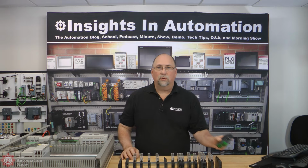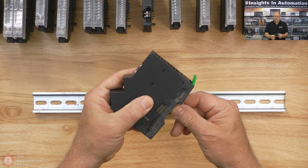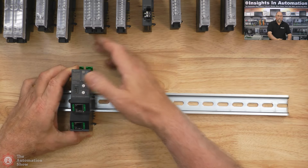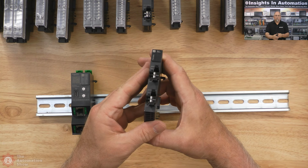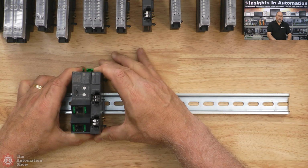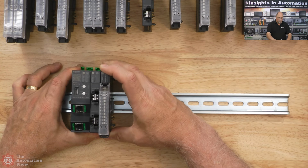But first, of course, we're always going to start on the leftmost side of the rail, which is going to be our NIM. Okay, I got the green clips up here. So I'm just going to put the top on first and then go down and lock those in. It's as easy as that. Next, I got the power supply module. Again, I'll put that on here, a little to the right, go down, and then slide it together and lock that green tab. Okay, and that's how easy it is to go through and assemble.